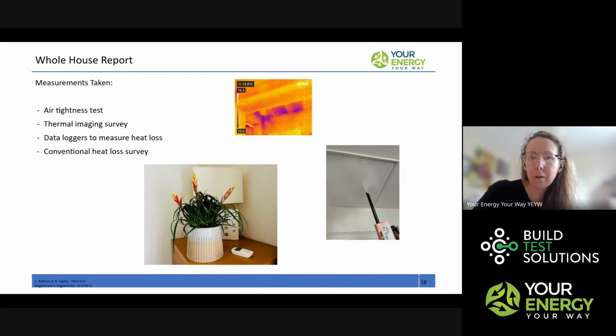I made the assumptions about the U values of this bit based on the age of the extension. And when we'd done all our measurements, did our install, everything's working perfectly, except that in this room, we did not put a big enough radiator in. When I came back to it, I looked back through and realized that something is obviously not right with the insulation in this. That's a bit of external sealing. Something has gone awry there. That led to the kitchen being a lot colder than my calculations made it. So I guess just to illustrate, these things can catch you out in nasty ways.